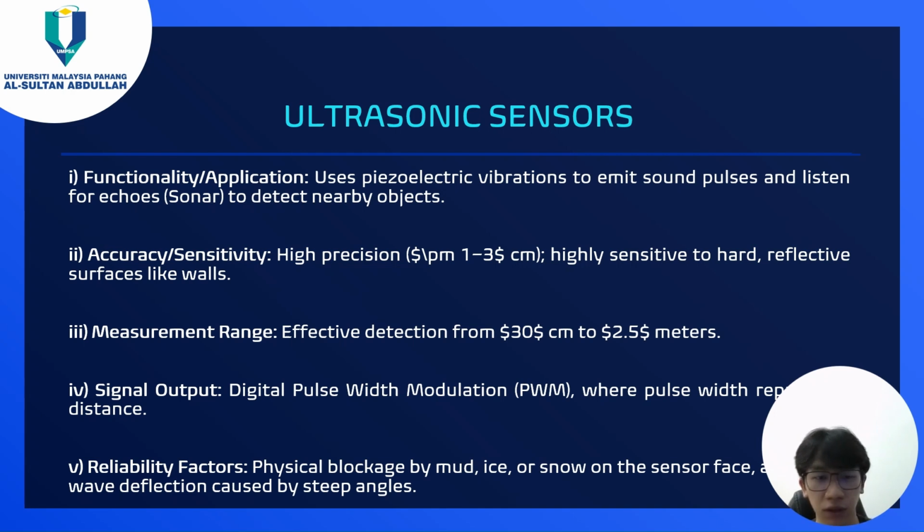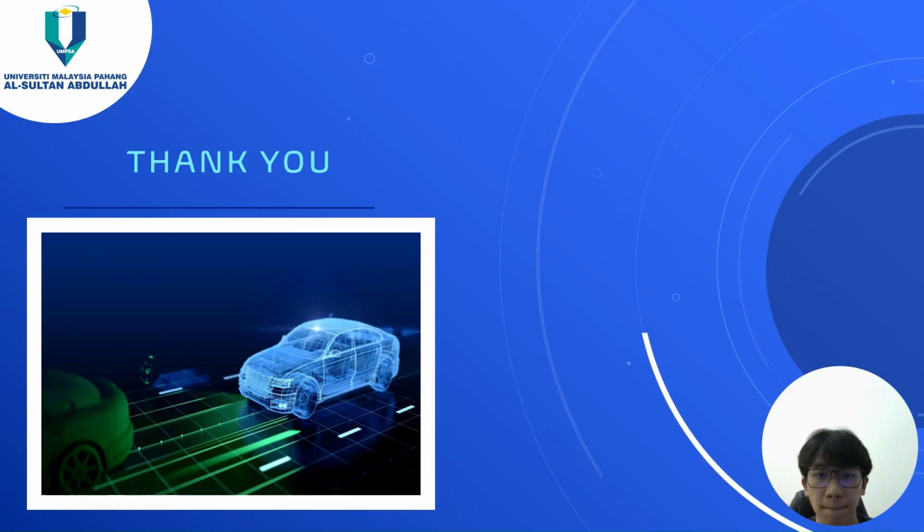Reliability factors include physical blockage by mud, ice, or snow on the sensor face. It can also be affected by wave deflection caused by steep angles. So this is basically the presentation from me for the ADAS, which is